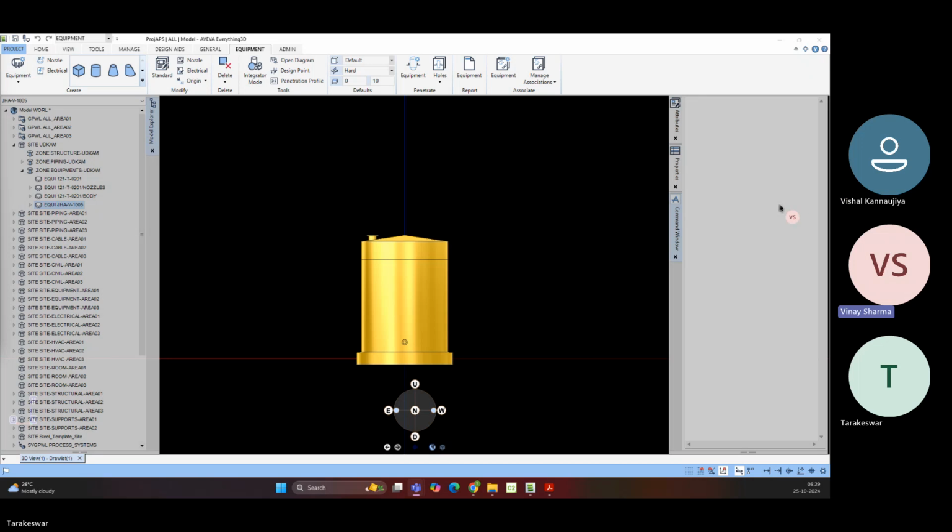The other is called explicit position. Explicit position means you don't know where the piping is coming from, so you just click randomly anywhere. From there you do the piping and make changes like by up, by down, and so on. In that case you know the exact position or coordinates of the piping. For example, in layout, 90% of pipings will be done by split piping in the initial stage, until you get the equipment layout.